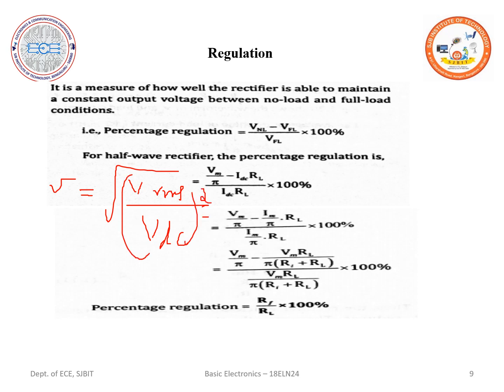Substitute, we know VRMS, we know VDC. When we substitute, we get our ripple factor as equal to 1.21, which gives an inference that 1.21% of AC component is present in the converted DC output by a half wave rectifier. So this is about the ripple factor.